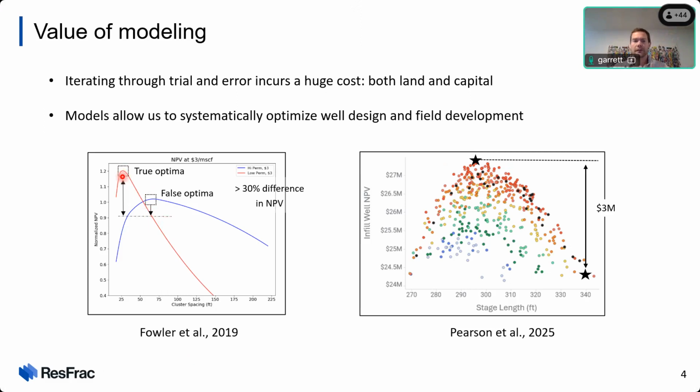So just from an energy balance and mass balance standpoint, if you have the high permeability and you know the production rate, that means that you're producing from a much smaller fracture area, and you would not see communication between wells at the distances they were seeing communication. So we were able to validate this lower permeability assumption. That has been consistently corroborated through the Marcellus in the years since.